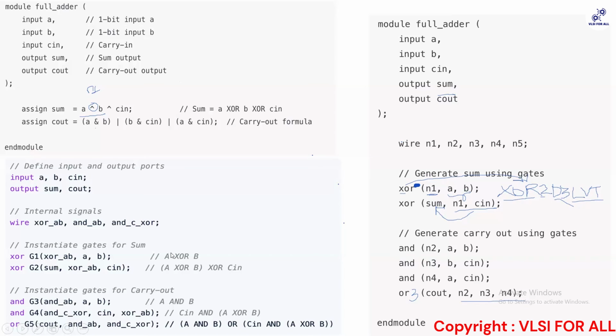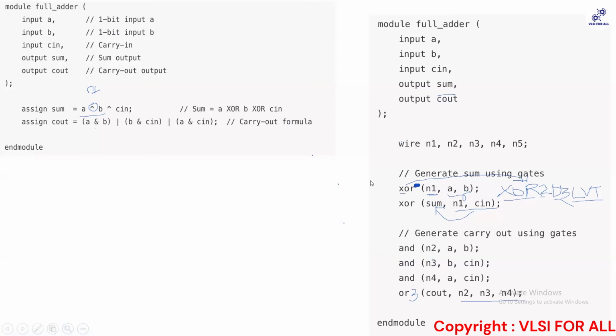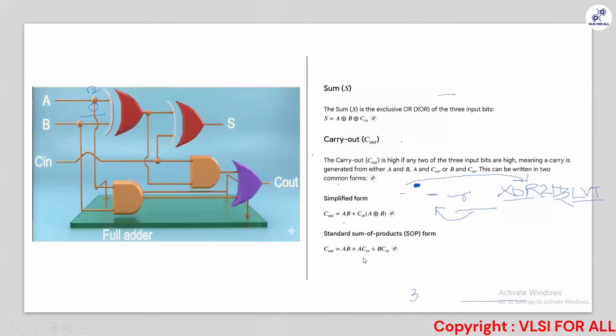Because if you look at the earlier picture which I depicted, it shows that instead of AB plus AC plus BC, you could have done it in the form of AB plus C in XOR A and B, right? Guys, you remember the first output, where the first way it generated was using this SOP format. And there it found out that the number of gates that can be used are larger.